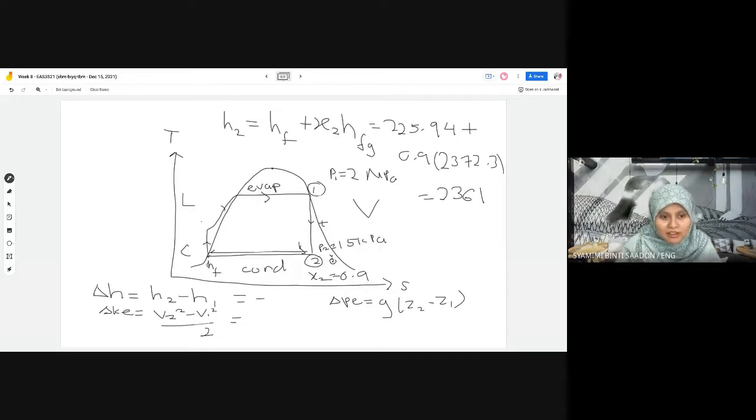The main consumption of energy is the enthalpy, which means the internal energy, pressure, temperature, etc. Potential energy is around negative 0.04 and kinetic energy around 15 kilojoule per kilogram, but the enthalpy is around 800, 900 kilojoule per kilogram.